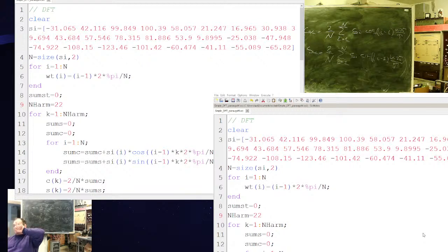I should have enough samples in a period to maintain the rule, but the sampling frequency, or 1 divided by the distance between samples, should be at least twice the highest harmonic. The highest I can get here is 19. And the moment I attempt to calculate harmonic number 20, yes, it's a complete disorder.